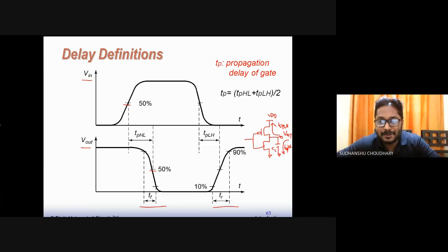Yes, so obviously, with capacitor, you added some more capacitance here. Earlier, in whatever simulations you had done, maybe some default capacitance was used at the output, and then you added extra capacitance to the output node. When you add an extra capacitance at the output, obviously the propagation delay will be larger. Earlier, the drain diffusion capacitances were already there, and the tool may have already considered that, but then you also added extra capacitance. These are in parallel, so they will add up.